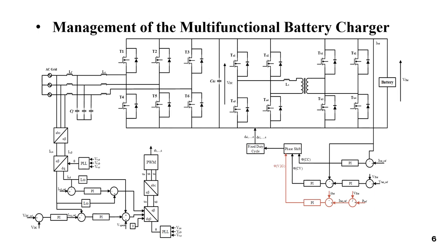The battery then begins the succeeding charging phase, where the voltage is held at its maximum value and the current gradually drops until it reaches the battery's cutoff current, with the battery's state of charge reaching its maximum value.